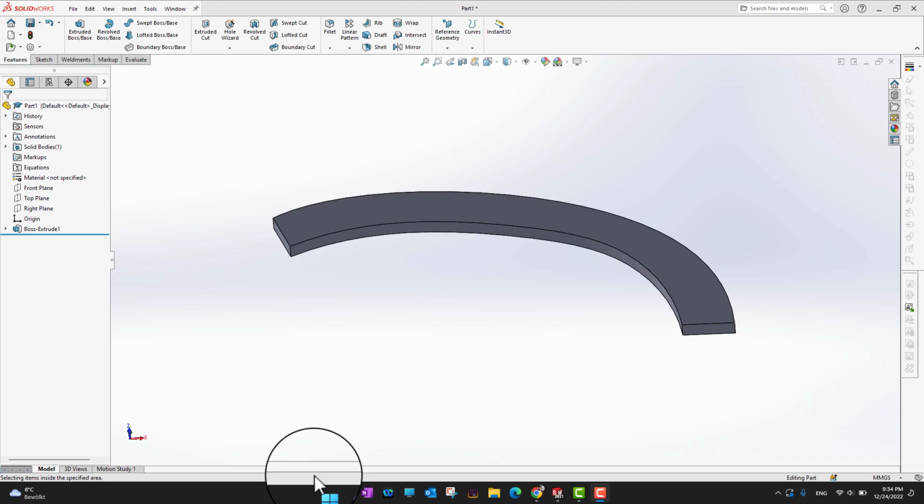Thank you for watching, and in this video I'm going to cover the asset publisher for magnetic mates. As in the previous video we already saw the magnetic mates are awesome, but before using the magnetic mates we need to use a connection point. So in this video we are going to use the asset publisher to create connection points for the magnetic mates.